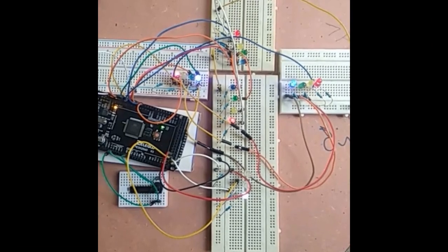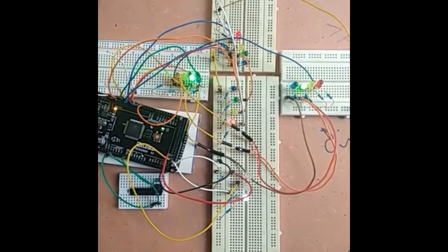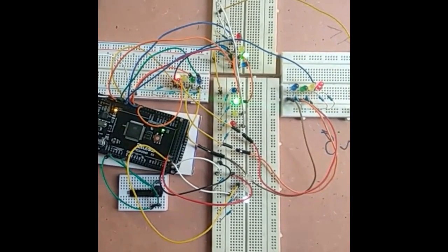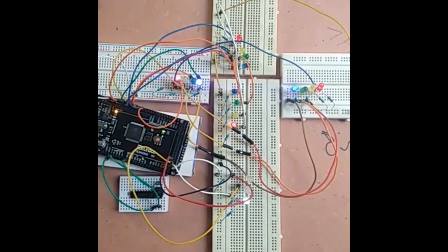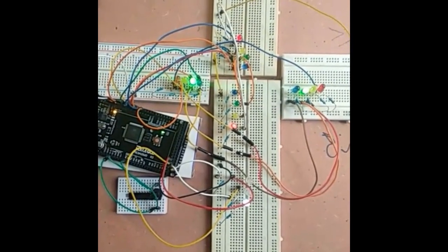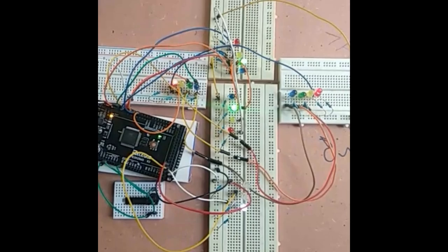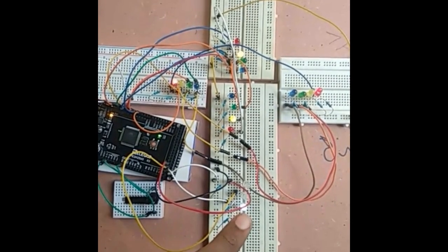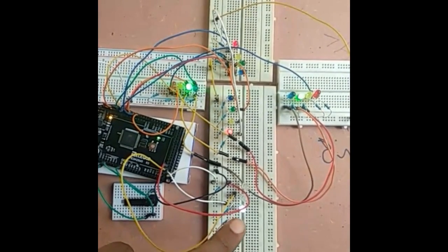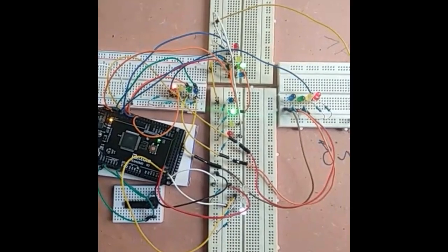In this video, we will see how to control the delay between the states using a potentiometer. In our earlier videos, we have seen how to read the potentiometer value using the analog input pin of the Arduino, and based on the value we are controlling these LEDs. These are white in color. So we have a total of 4 values. For 1 we will light the first LED, for a value of 2 we will light the second LED, for a value of 3 we will light the first and second LEDs, and for a value of 4 we will light the third LED to indicate a binary pattern.